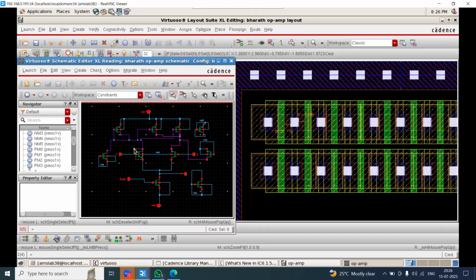If signals are coming in the outer corners of the devices boundary, in order to protect those devices, we will use half dummies or signal dummies. The name for this dummy is signal dummy or half dummy. When we are getting a supply connection at the outside corners, we call that device a full dummy, or full supply dummy.